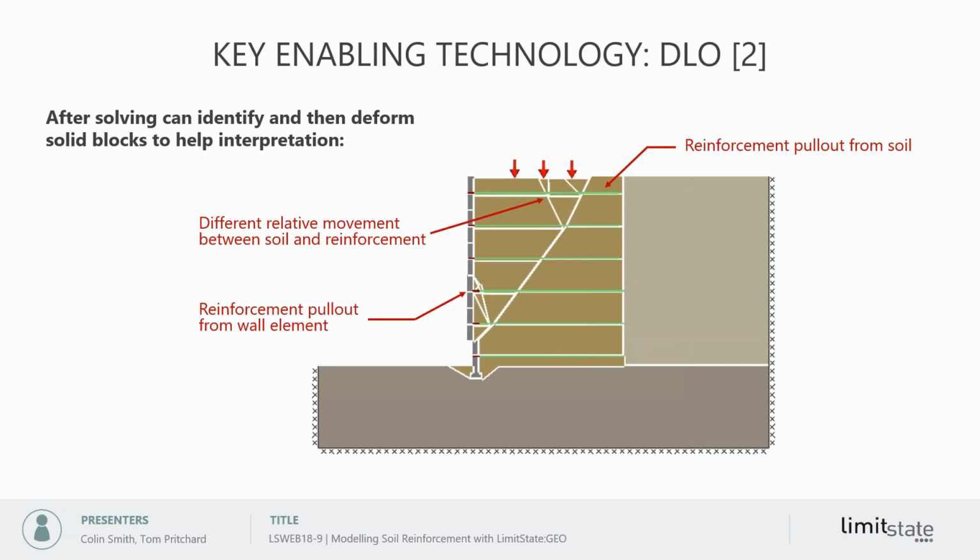So when we apply that to reinforced soil, we essentially include a special one-dimensional reinforcement element in the software. In a fully general analysis, we may have multiple wedges of soil moving in different directions relative to the reinforcement. So we cannot think about internal and external stability, particularly. We have to make sure that we model this in a fully general way. And that's exactly what's done in the software. It's modeled in a fully general way, but still adopting the same mechanics principles as in a classical analysis.